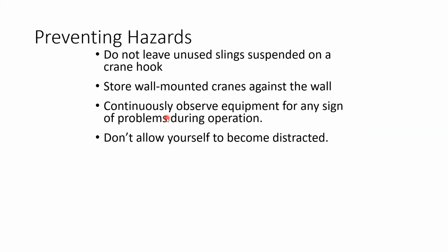Don't leave unused slings suspended on the crane hook. Store wall-mounted cranes against the wall. Continuously observe the equipment for any sign of problems during operation. Don't allow yourself to become distracted. All of these are administrative instructions, or administrative control.